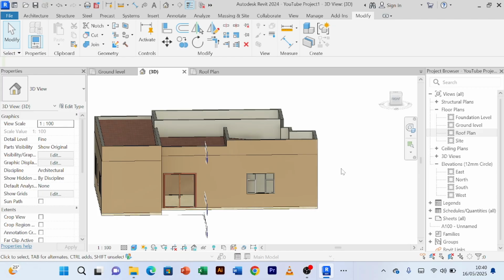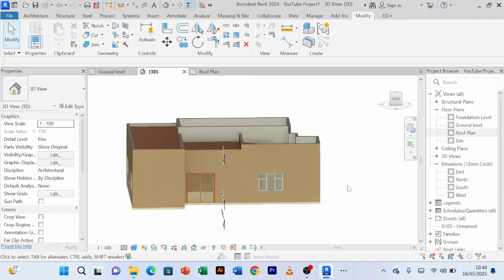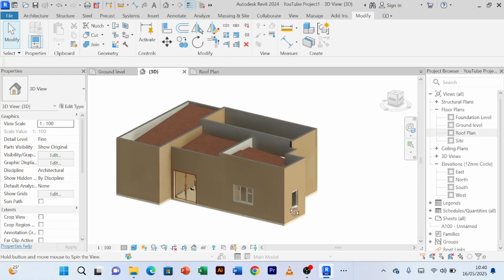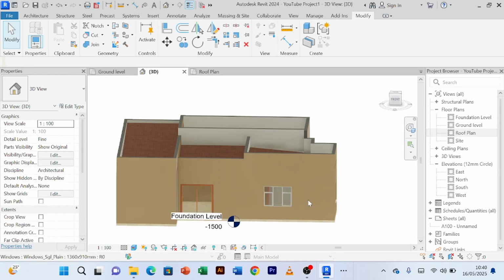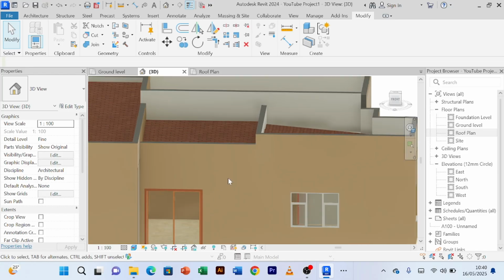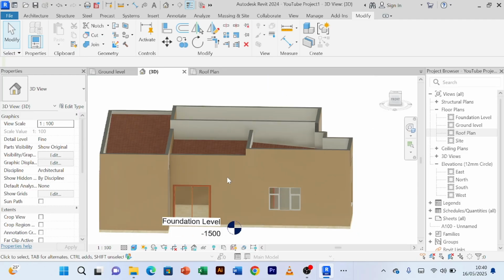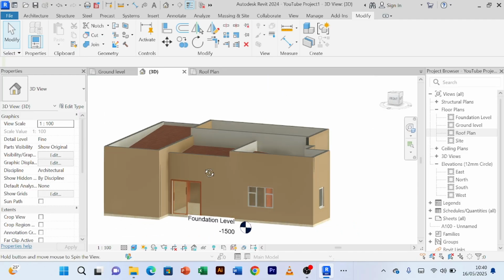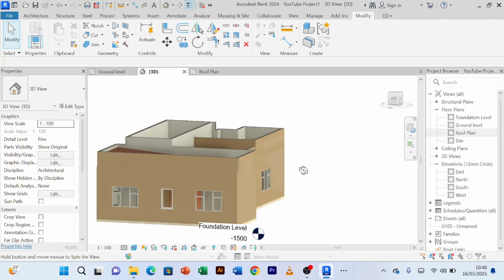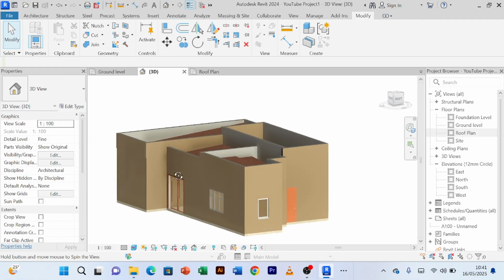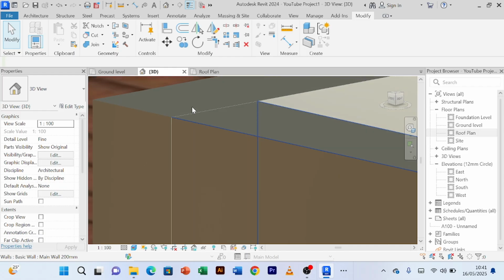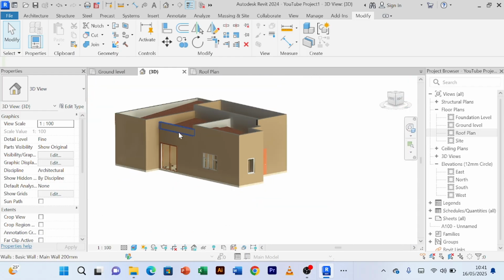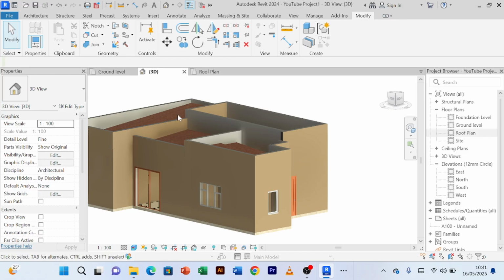So that is how you can do your roof and also hide it using parapet wall. This roof we created is called a lean-to roof. Some people call it hidden roof, but hidden roof can be quite many in number, because even if you do a flat roof, you hide it, it will still be called hidden roof. You can also do a hipped roof and then you still hide it. But this one specifically is called a lean-to because it leans towards the wall, like one surface of the wall, and then pours water on the other side.